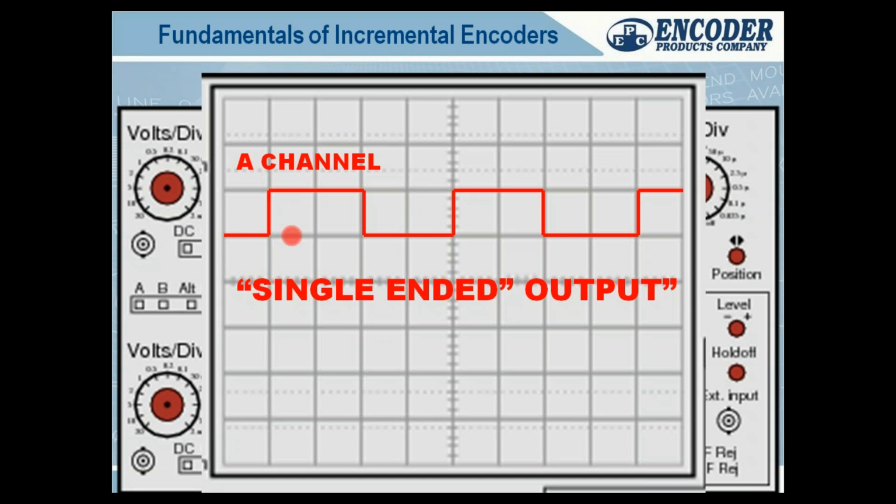One thing you can't do is this is called single-ended output. On a data sheet, you'll see the word single-ended or unidirectional. When you're counting these pulses flying by, one thing you can't tell is what direction you're spinning. Whether I read these from right to left or left to right, it's just a rise and a fall again. So if I have that encoder on a machine and I turn it clockwise or counterclockwise, the pulses look the same. So single-ended output is for one direction movement only. If you have it on a conveyor or a cut-to-length application or a belt, and that belt will never go the other direction, this is all you need. You need an encoder with one channel output, a 3-wire encoder, it's commonly called.